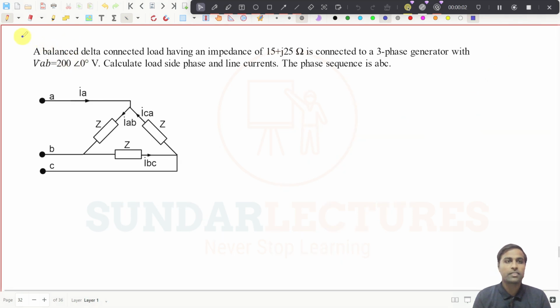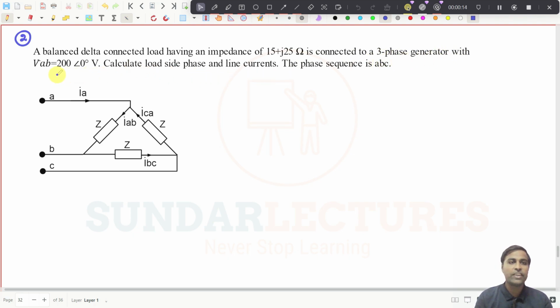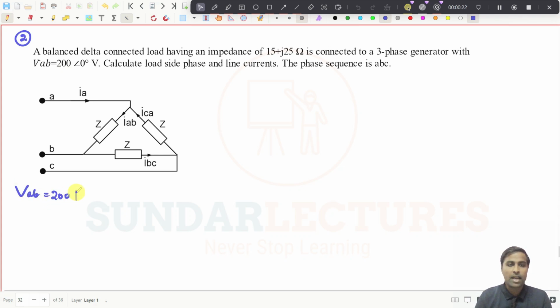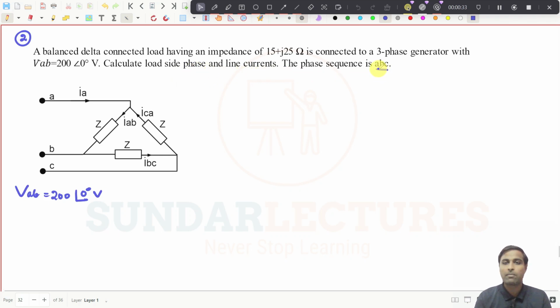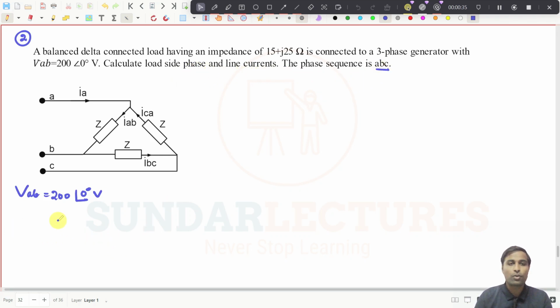So now you see this is the second problem, and in the second problem what they have given you is a balanced delta connected load having an impedance of 15 + j25 ohms, connected to a three-phase generator with VAB. They have given you the VAB value, which is equal to 200 at an angle of 0 degree volt. So this is the reference, right? Now VAB will be the reference, and calculate the load side phase and line currents. The sequence is ABC. They have asked you to find the phase and line current.